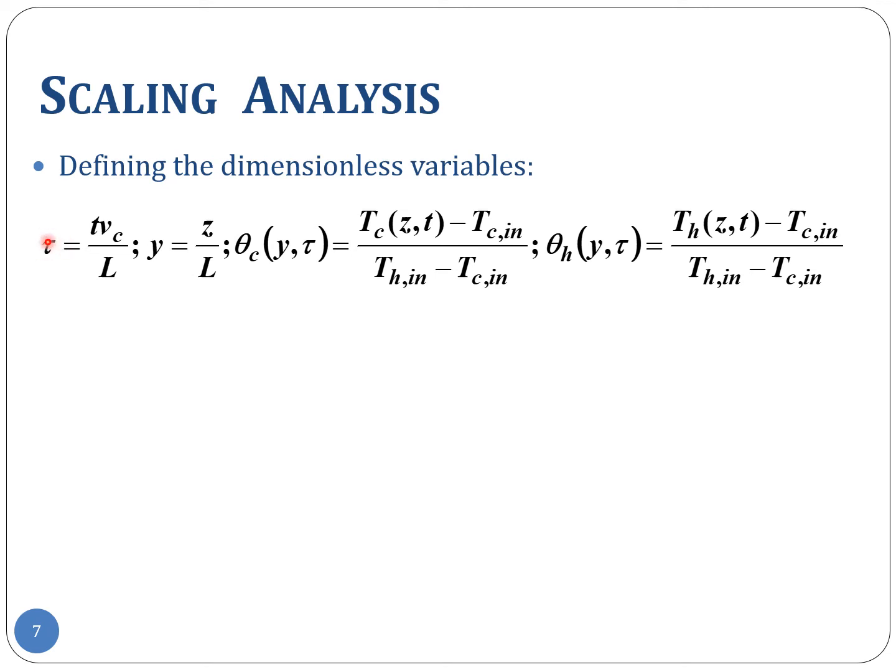So that is indicated by the symbol tau. L by Vc, by the way, could be called T bar. For example, it is the mean residence time for this plug flow. If it is an ideal plug flow, then there is only one value for that. I mean, there is no distribution of that residence time. If it is not an ideal plug flow, then there will be a distribution of the residence times.